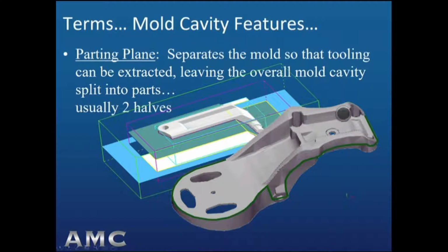At the lower center is that casting that we've already seen once, and if you look at that green line from the center left on down through the middle portion of the casting, up and around and over to the plate part of the casting, is what we call an offset parting for a sand mold to create that mold cavity by using the geometry of the parting plane to eliminate cores.